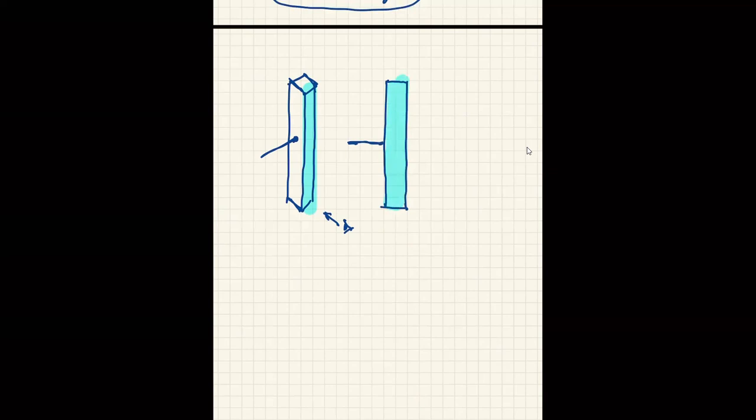Hello? Yes, yes. Good. So now when I apply compression, because of the presence of this bracing, this compression member is going to dance like this. It cannot dance here because of the presence of the support. All right, so that becomes my unbraced length. That too. That's the unbraced length, not the length of the column, you see?